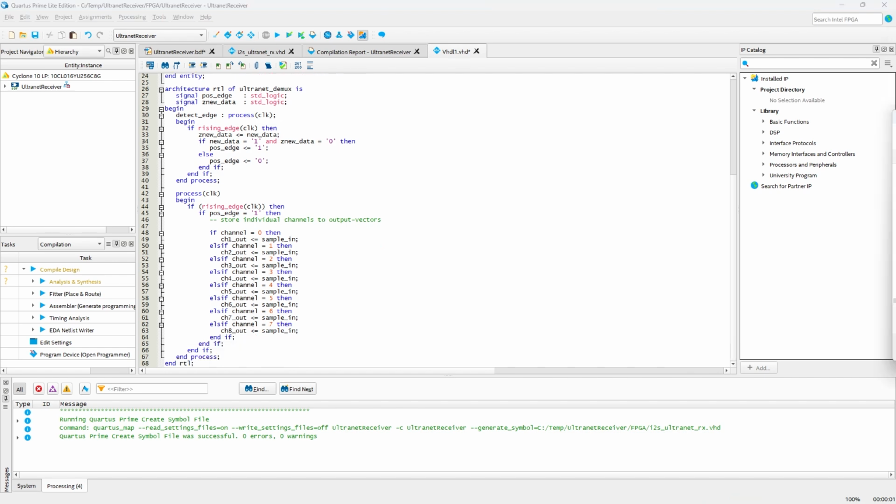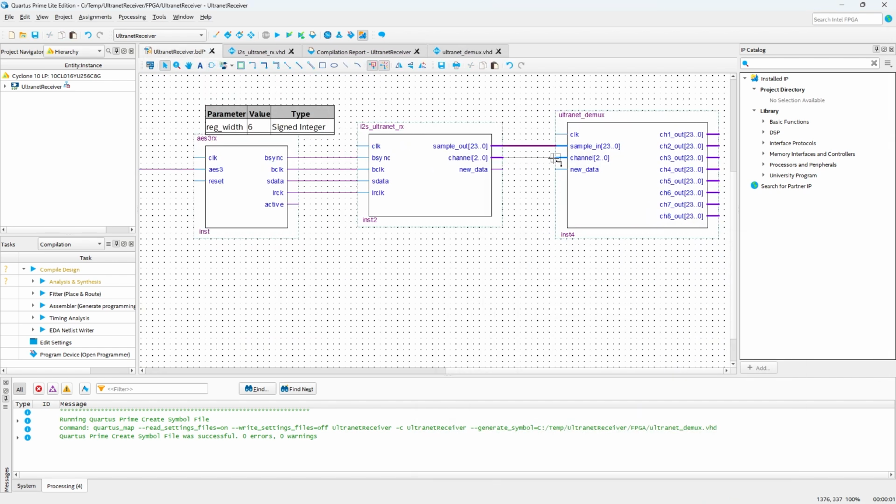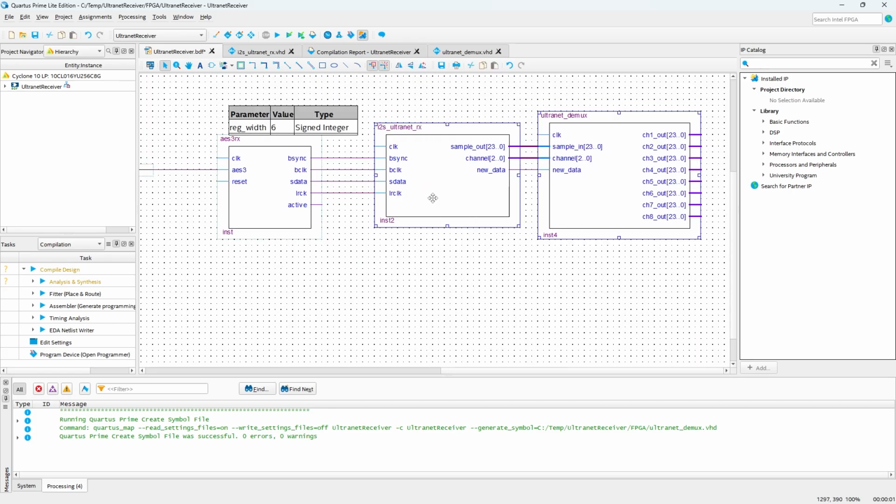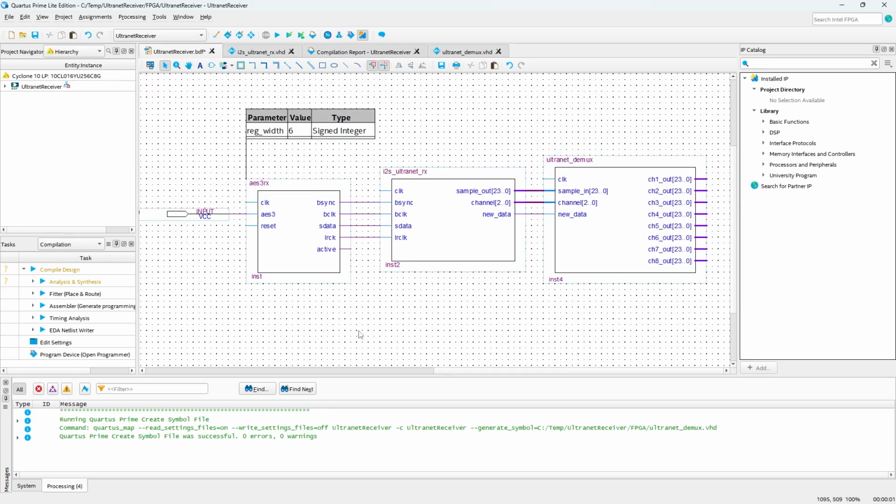From now on, we can do everything imaginable with these simple audio samples. The most obvious thing would be a test output to an analog system. But how can we get the purely digital FPGA to output analog signals? Thanks to standardizations, we do not need to do much different than when receiving the audio data. We simply use AES-EBU again and output a stereo signal on a standard converter like this device here. According to the specification, an RF transformer should be used, but a direct connection between the Arduino and these coax input here should be fine for testing.